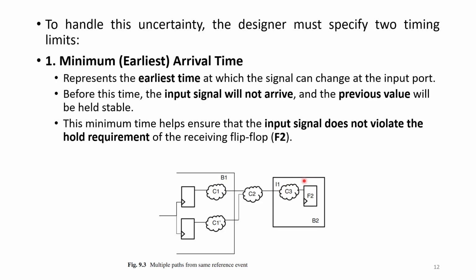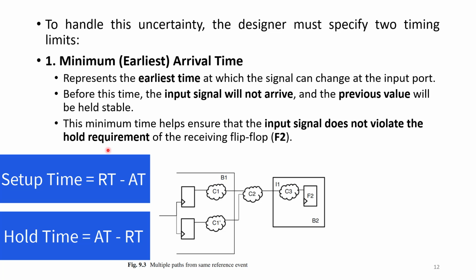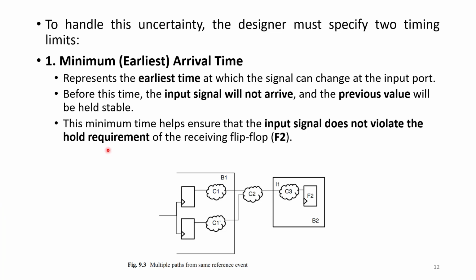So here we are checking the hold condition. Here you need to know, generally we know the setup and hold. For setup, generally required time should be greater than the arrival time, whereas for hold, arrival time should be greater than the required time. So let us see it by means of some examples in the upcoming slides.